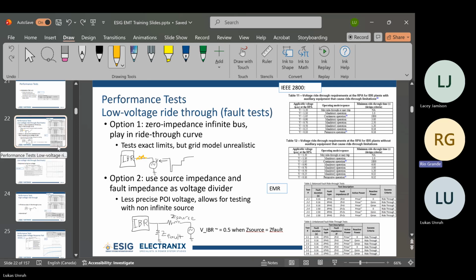We haven't, I don't know if that's, it hasn't been proposed in our requirements at least. I think maybe some other grids have done that. But it's something to maybe add at some point. But it's usually not tested because it's not in the model space. And that's a limitation, because the thing that causes issues with cumulative fault events is thermal problems, heating up of equipment or copper circuits and stuff like that, and those aren't in any of the models. So literally, the cumulative ride-through representation is a counter.